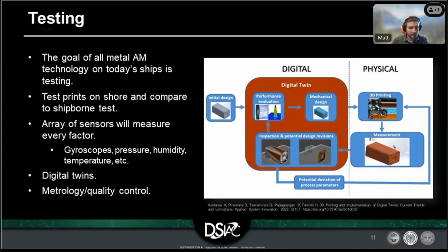And I'm going to do metrology on it. I'm going to measure all of its components, give it some sort of report on that. That's going to be included in the digital twin there. I could do some analysis based on that. That's going to be included on there. And then let's say I'm going to do rework in 5 years or something. So I'm going to do inspection on it, NDI inspection, going to make sure there are no voids or issues with it or cracks. Then that's going to be carried on into the digital twin.